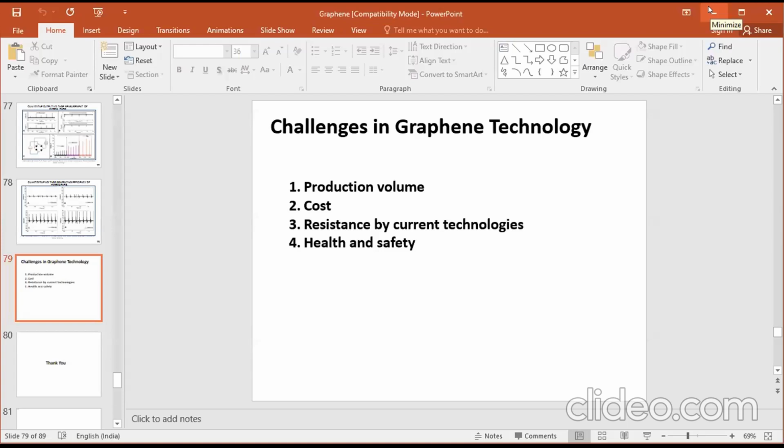Yeah, I think you can add graphene to many of the metals, so that is possible. Currently we are involved in adding graphene to copper, because, as I told you in the discussion, graphene has almost 100 times more electrical conductivity than copper. So we are actually adding graphene to copper, right? This improves the electrical conductivity so that the I squared R loss can be reduced. The heat produced in electric motors, especially for electric vehicles, can be reduced. That is around 35% of the total electrical loss. That can be reduced by improving the electrical conductivity, just reducing the resistance of copper.